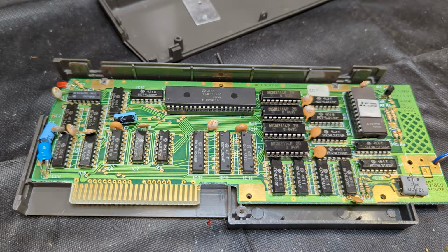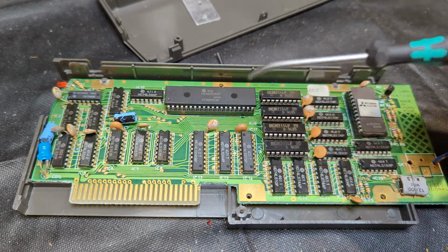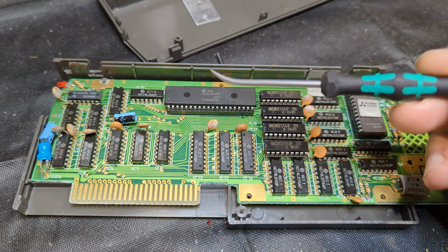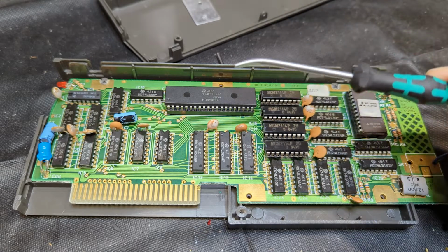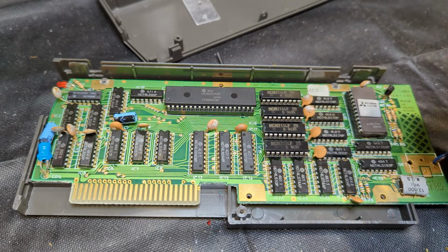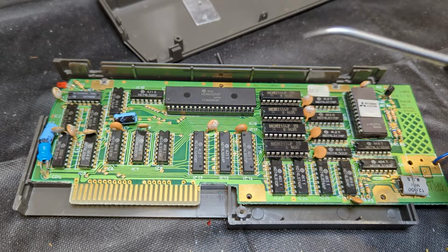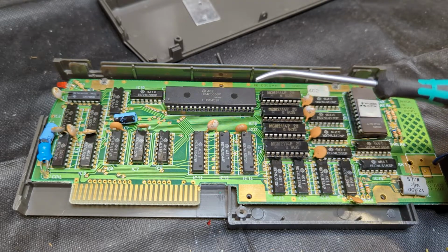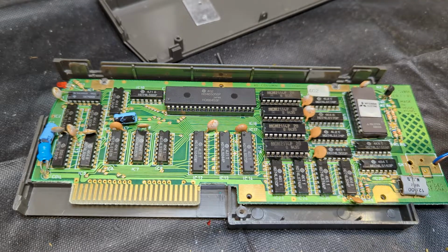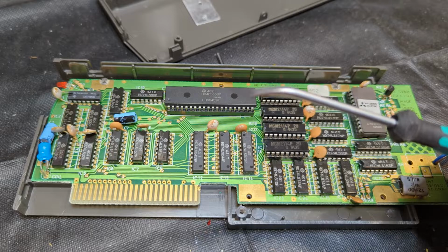So the Spectravideo 80 column card is based around the Hitachi 6845 CRTC controller chip. This was actually made by other manufacturers as well. I think Rockwell, Motorola, and maybe a couple of others. This is the same chip that was used in the BBC Micro, the Amstrad CPC, and even some of the early IBM compatible video cards. The datasheet will tell you it's designed to address 16 kilobytes of video memory, but the BBC in particular did some creative external logic hackery to get it to address 20 kilobytes of video memory.